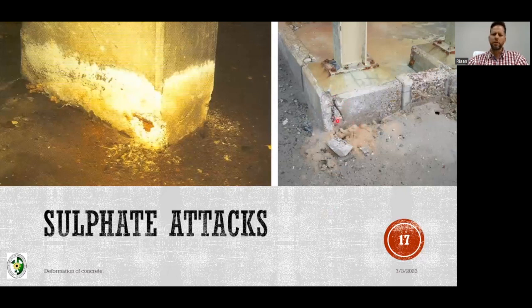Sulfate attack, as I mentioned, happens as soon as something can get into your concrete with moisture, it is able to attack your concrete. And we discussed in the previous session that if you are able to densify your concrete matrix, if you can prevent stuff coming in there, if you can reduce your macropores, there's not much to be done about the micropores. The micropores are a chemical reaction that is ongoing within your concrete, very fast in initial stages, and later on with whatever was inside your cement or with what you've extended.